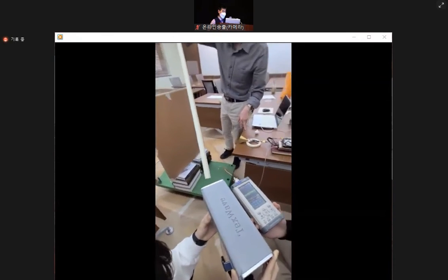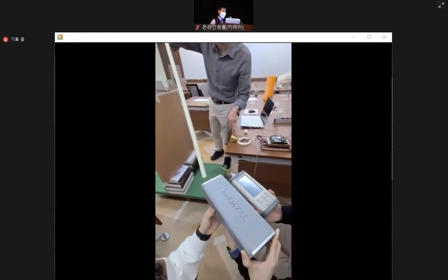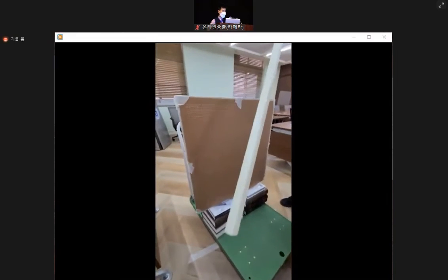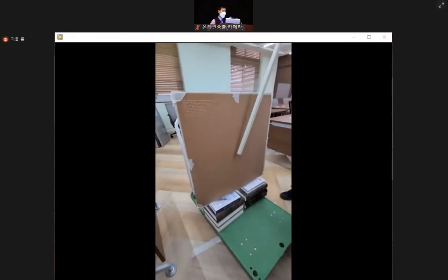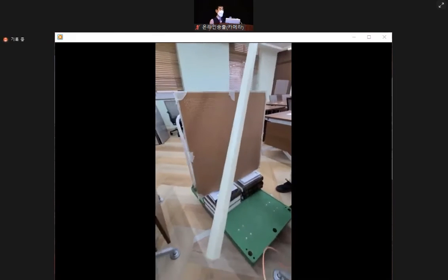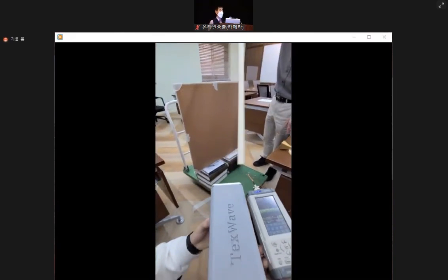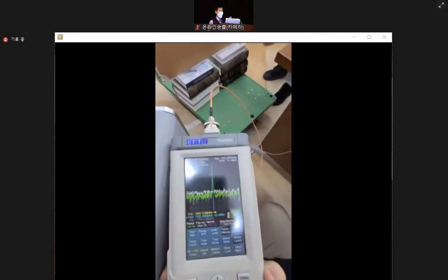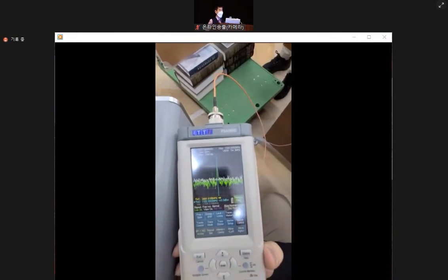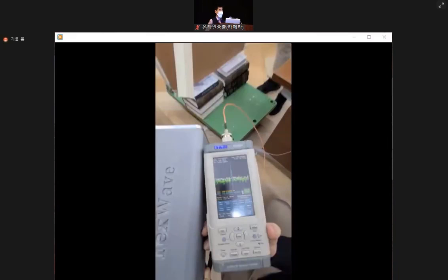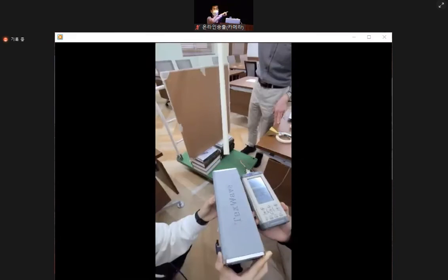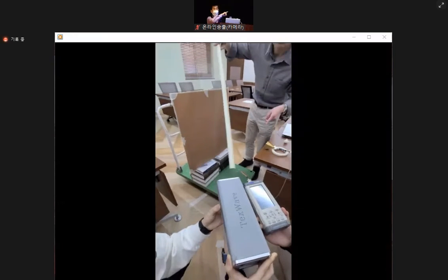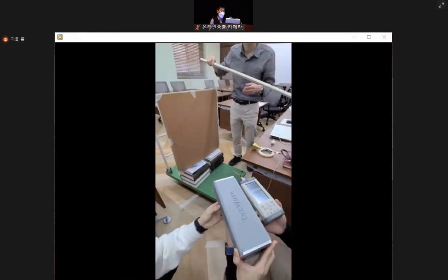Now it is positioned at the angular position of 41 degrees. If you extend the line from the center of the metal surface, this is 41 or 45 degrees. So minus 41 dBm is read there. Did you see a spike there? This is hopefully the strongest point. That means, at that angular position, or in the azimuth plane, that has a certain value of strength.